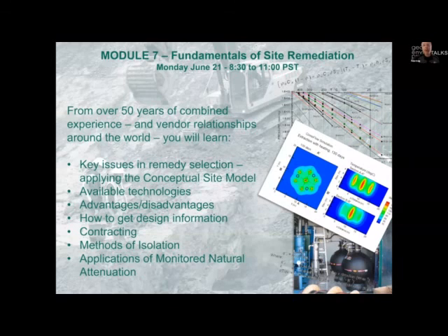And we'll talk about how you contract this, how you actually tender these projects, how you get them delivered, owner role, consultant role, contractor role. We'll talk about not alternatives to remediation, but kind of long-term management approaches that help you come to a cost-effective closure, which could involve isolating portions of the site or removing the hotspots. And we'll talk about applications of monitored natural attenuation. One of the things that we see a lot is a synergy between risk assessment, monitored natural attenuation, and remediation, where the most efficient and sustainable allocation of societal resources is removing some critically hazardous material, risk managing the rest, and allowing natural systems to recover.